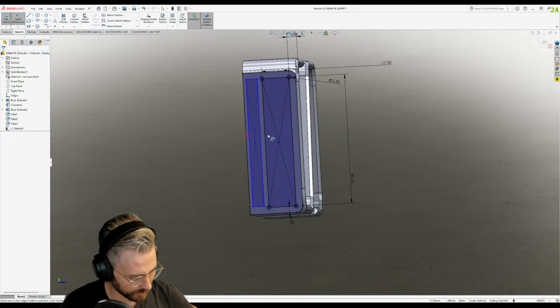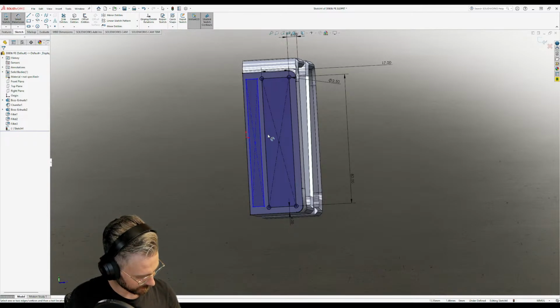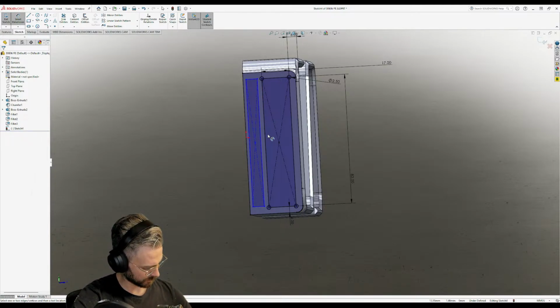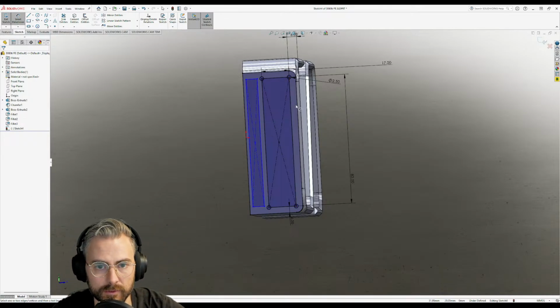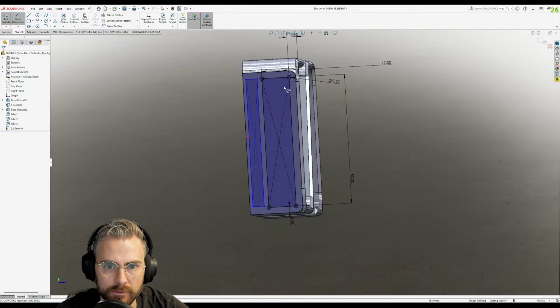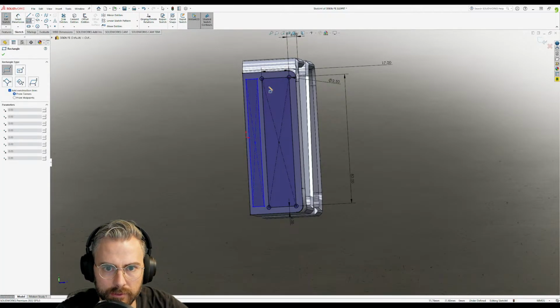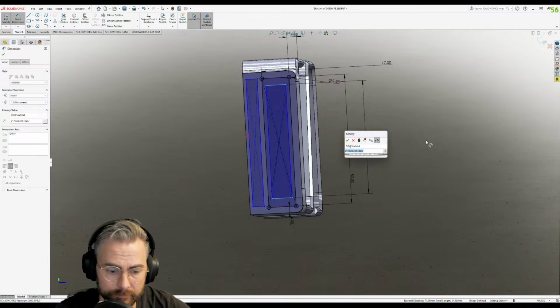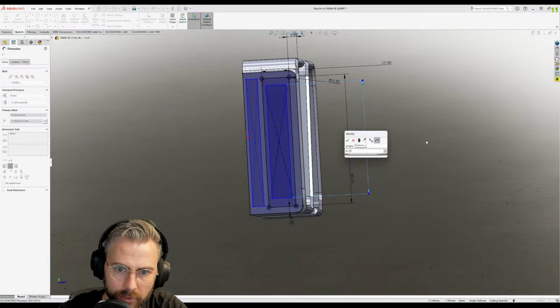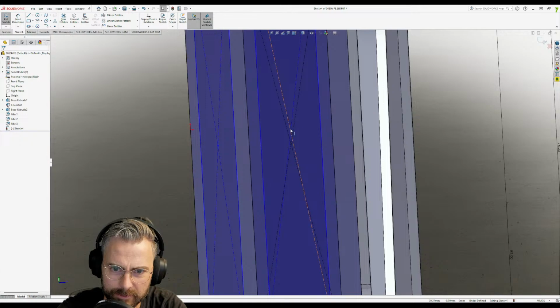Now we've got a cutout there, which is precisely 22.4 by 76.26. 76.2, well, probably 76.25, because usually they'll have... all right, so we're going to go in here and draw another rectangle within this rectangle, and it's 76.25 high.